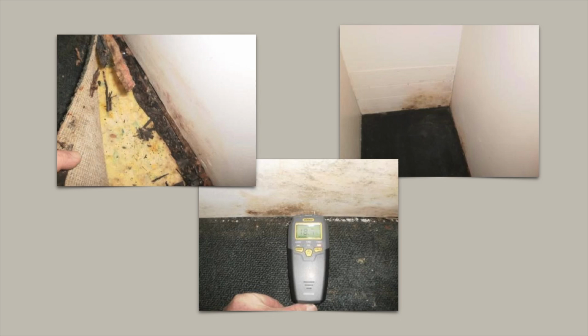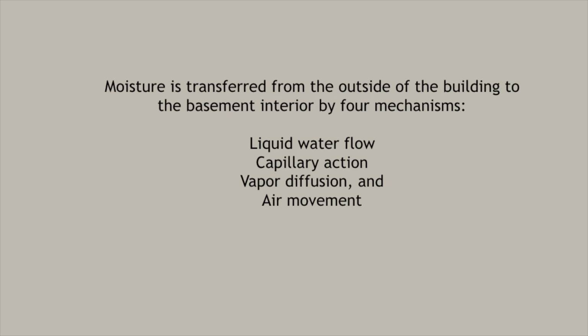Deterioration of carpet or rotting wood. Deterioration of wood headers, joists, beams, sill plates, and rusty metal columns. Staining of wall covering and blistering drywall or sheetrock. Efflorescence or spalling on concrete or masonry. Moisture problems in existing basements are very common too, but these problems often are not understood or repaired.